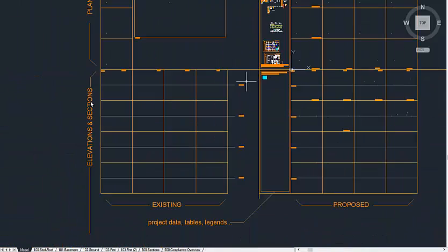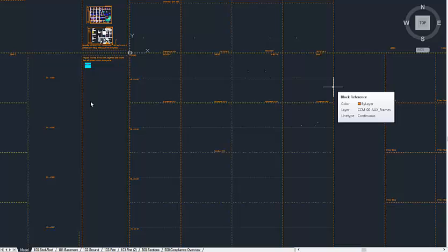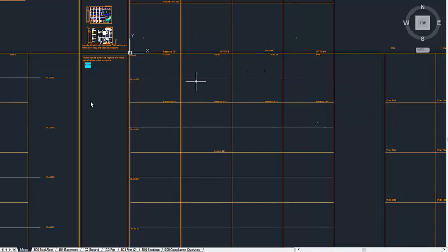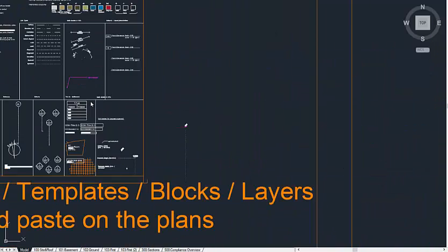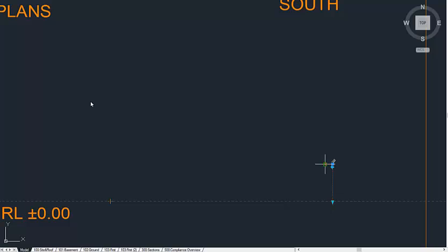Now this is important because we normally set the level 0, because normally everything we do is in Sydney, so it's normally between 2 meters above ground level and 100 meters above ground level. So by editing this block and moving this black line somewhere that it makes sense, we can have the project in reference to layer 0. So if we then use this and say that this is pointing at the ground level, then region will tell us about 20 meters above ground level.